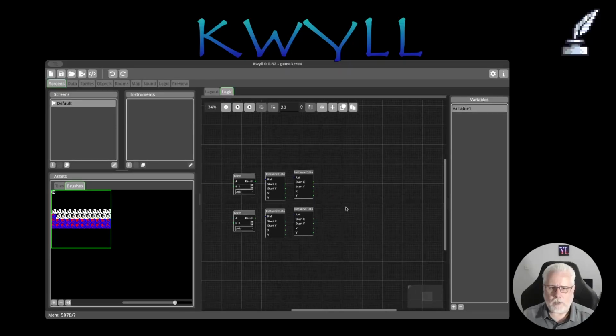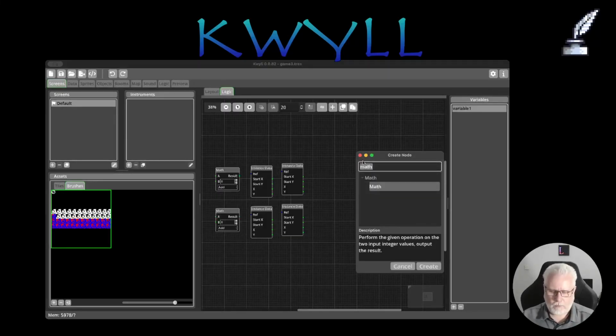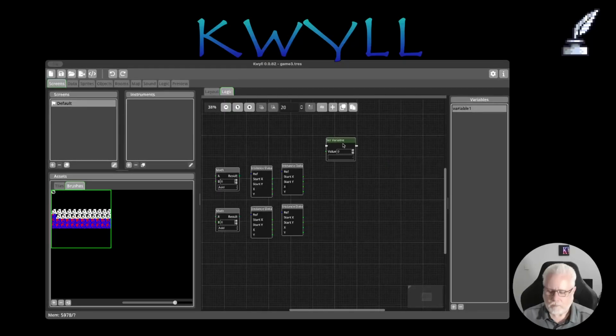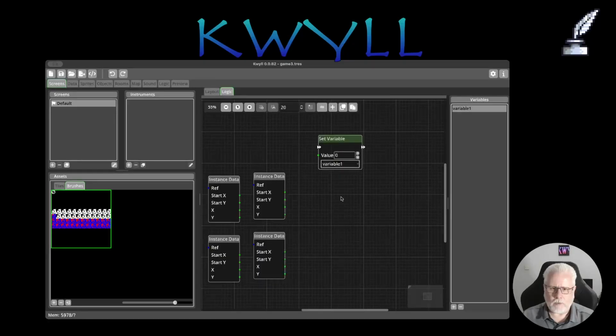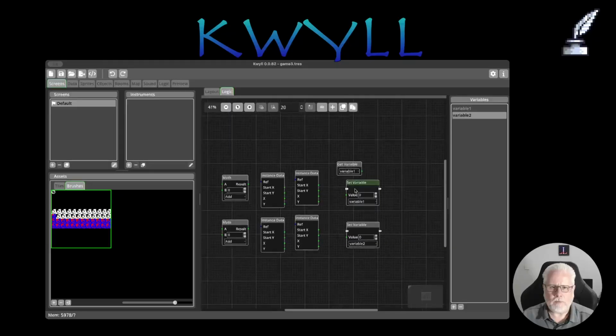For accessing the variable values, either setting or getting, you use a set variable or get variable node, and that allows you to just choose the variable. Or much more conveniently, if you drag the variable in with the left button, it's a get, and it's already populated with the correct variable, and shift left button will bring in a set. That just makes it really easy, so if you had multiple variables, you could bring in that and it automatically populates it. So just a convenience factor.